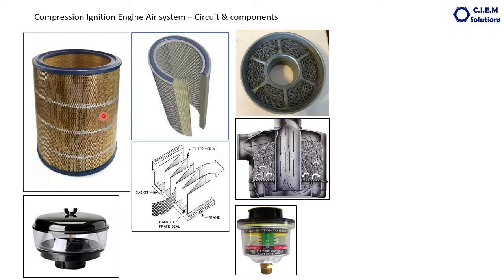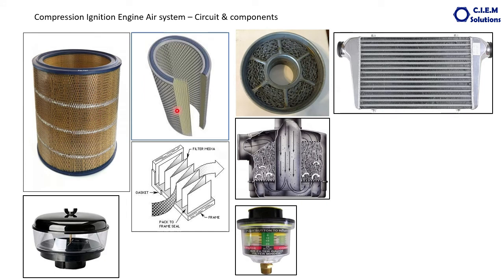If they don't clean the filter and run the engine with a clogged filter, sufficient air will not go to the engine and the engine will be starving for want of oxygen. Fuel is wasted, there will be an enormous amount of black smoke, loss of power, and so many further consequential problems. Filter is over.